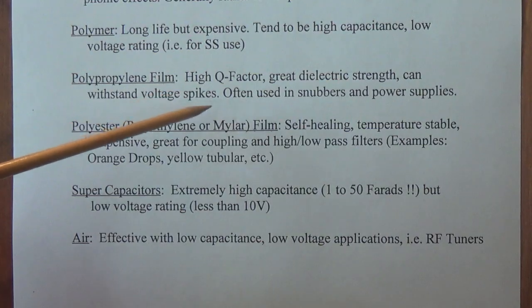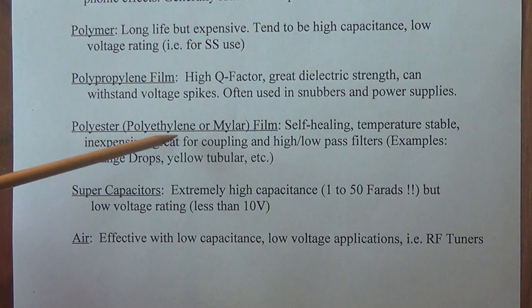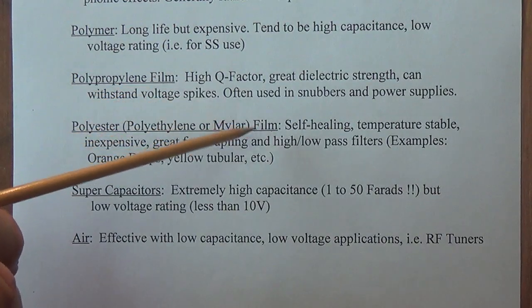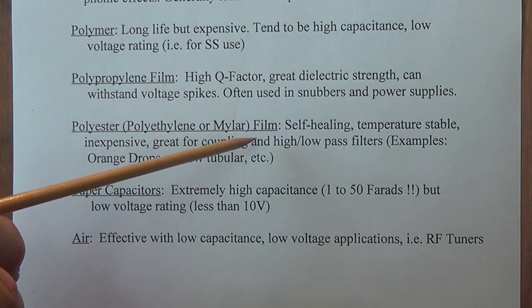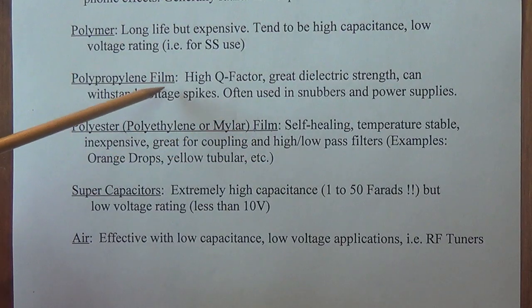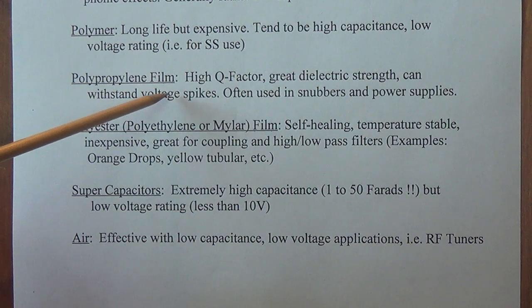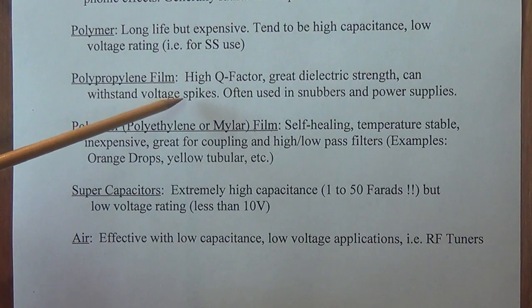So this is a little more modern way to create both capacitors and resistors. We'll see metal film resistors now have kind of taken over. The reason being, I'm assuming, that it lends itself more to mass production, probably a little less expensive, and gives you really a good precision because you can control the thickness and consistency of that anodized layer very closely.